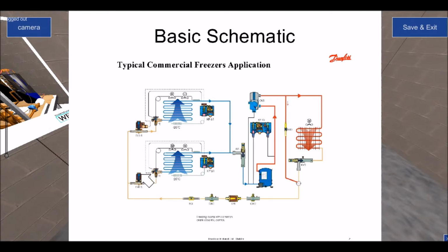So in other words, the solenoid valve becomes de-energized. So we refer to it as being de-energized. As soon as that coil is de-energized, there's a little spring on the top of the valve stem which will force the stem back down into the body of the valve. Okay? And once the stem is in the body of the valve, it basically then will prevent any refrigerant in this liquid line from going past the solenoid. So in other words, it doesn't allow any of the liquid to go through.